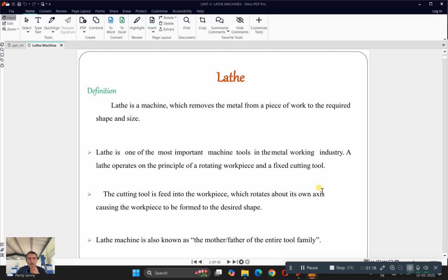But in the case of a subtractive process, such as lathe machines, we have something called a billet, which is a larger size of the actual product which we require to manufacture. Initially, the size and shape of the raw material will be very large when compared to the final output that we desire. So using lathe machines, we need to remove the material stage by stage, step by step, so that we will be able to get the final output. So this lathe comes under the subtractive process of manufacturing.